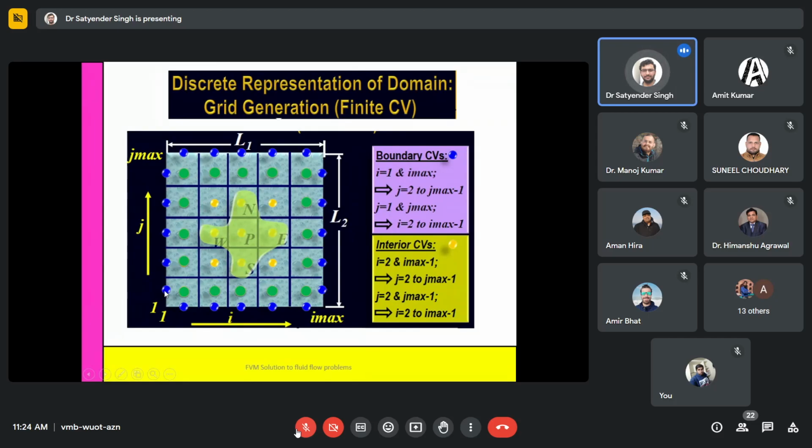When you are using any CFD software, there are some boundary conditions you name, like in the meshing, inlet, outlet, or wall as insulated, symmetry or open. Pressure maybe you assign, and you assign these values at the blue circles.